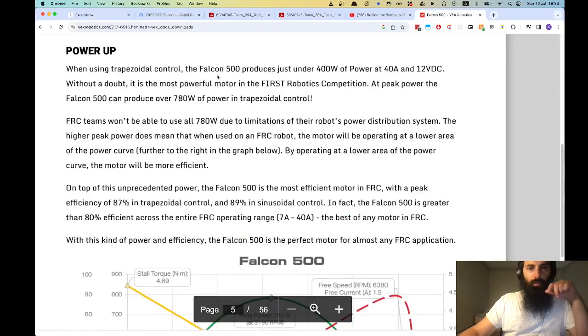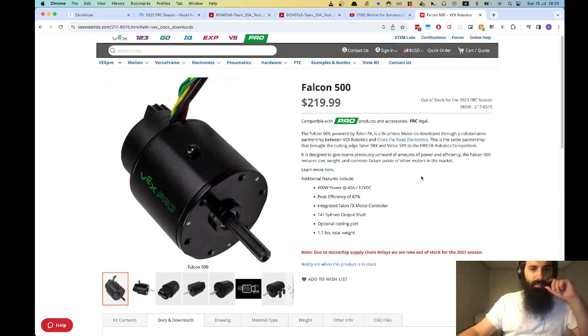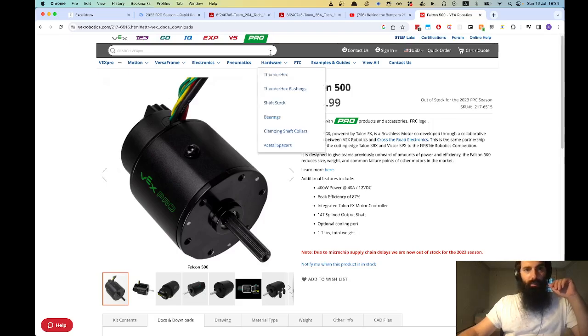So that's a motor. When it becomes necessary, we will get into the encoder situation. The encoder is a way to know how fast or how much the shaft has turned. So for example, things that need precise speeds or precise distances, like driving in autonomous, you're going to need to heavily use the encoder. Or in an elevator subsystem, you'll heavily need to use the encoder. But for the intake, it's not so necessary to have the wheel spinning at a certain computed velocity. So I'm not going to get into that for the purposes of this.